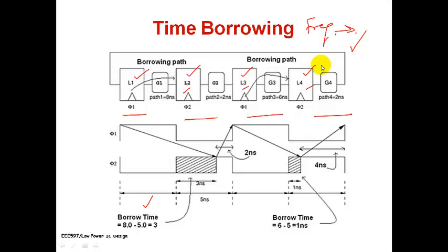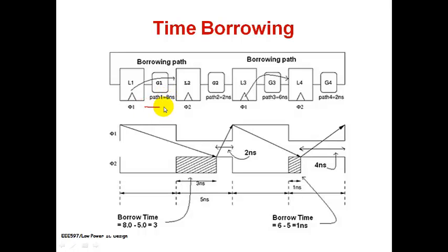And this way it will not be possible for the same flip-flop based circuit, because in the case of flip-flop based circuit, given with the maximum time of 8 nanosecond, I should have gone for all these stages 8 nanoseconds duration only.